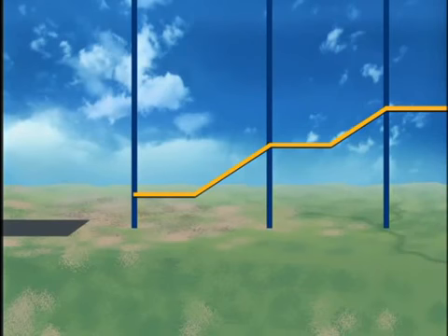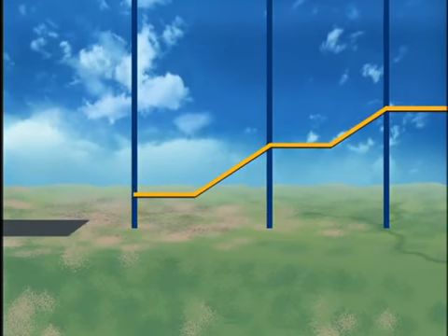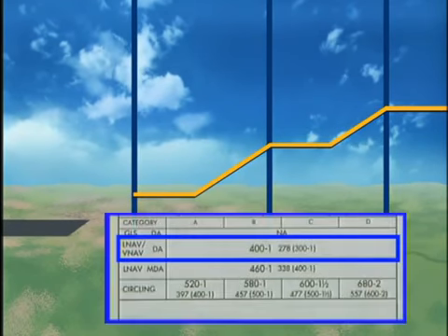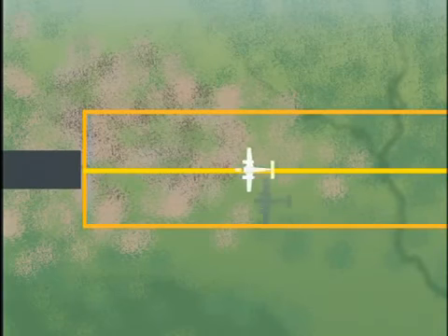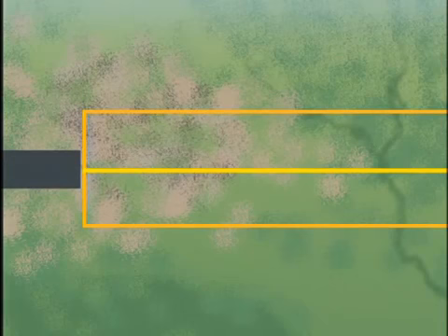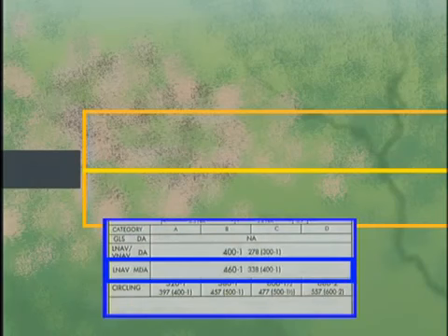LNAV, VNAV minimums are flown using a descent path generated by onboard navigation equipment. Since vertical guidance is provided, the minimums are published as a decision altitude. Use of the VNAV DA is subject to appropriate flight crew training, proper equipment, and operator approval. LNAV minimums are designed for non-precision approaches that only provide lateral navigation. Because vertical guidance is not provided, the minimums are published as an MDA.